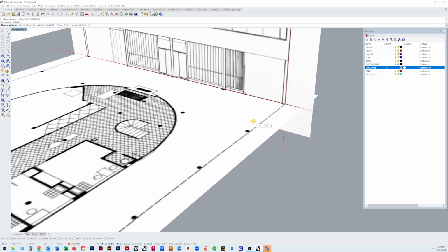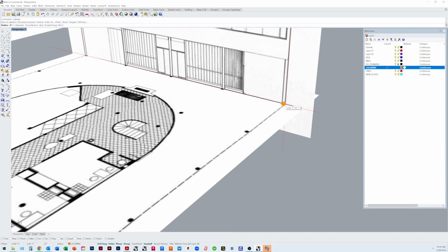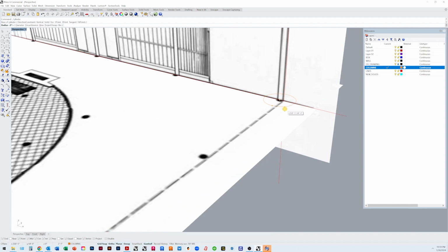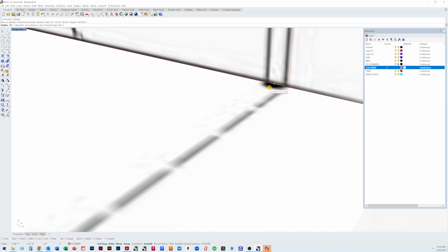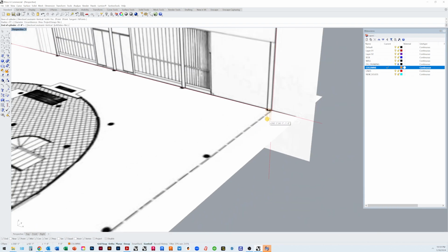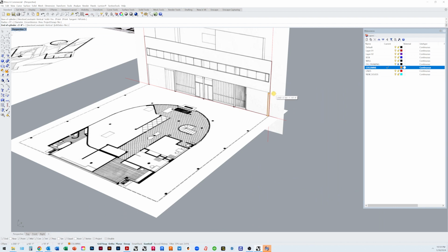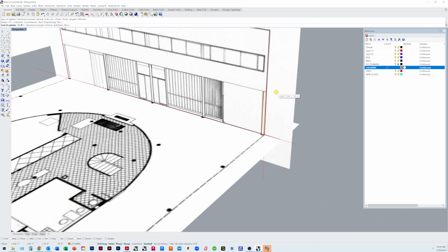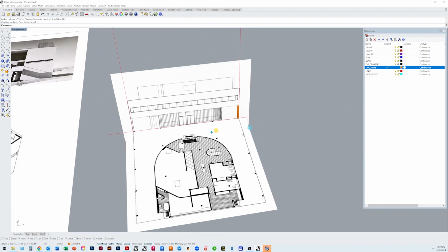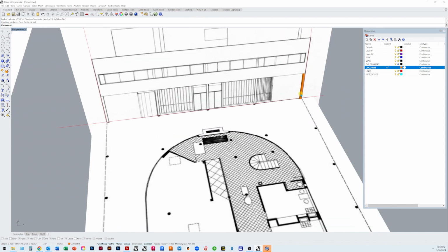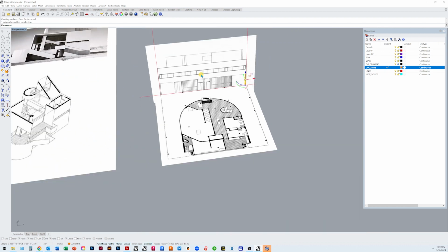And remember, we'll be drawing on the ground plane. So I can actually find the center of that column and give my best estimate for how big it is. And then extend it, at least to start with, up to where it's showing it to me in the elevation. Right? Once I do that one, I can take it, and we're going to assume all the columns are the same size. And I think we can also assume that this building is symmetrical across the center.